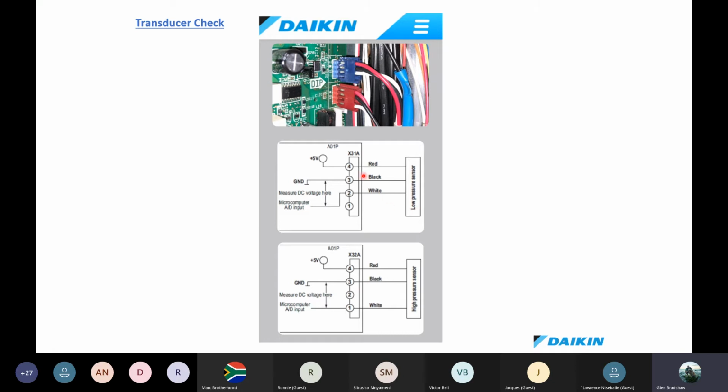So you'll see the low pressure uses pins 2, 3, and 4, while the high pressure uses pins 1, 3, and 4. Okay, so they're not interchangeable. If you plug them on the wrong plugs, obviously you can match them by color, but if you happen to get them in the wrong place, the unit will start giving you JA and JC alarms. Okay, so just be very, very careful of that.